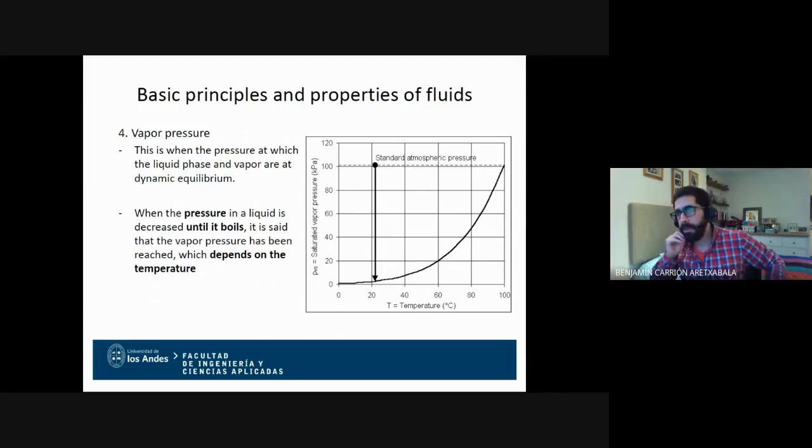This happens for several reasons, but the typical example is that water is actually a mixture of molecules. There is no continuum of water; there's water, and everything else has a lot of voids in it, right? When the pressure is too low, you allow these small voids to grow larger. And as they grow larger, they become unstable and then collapse onto themselves.